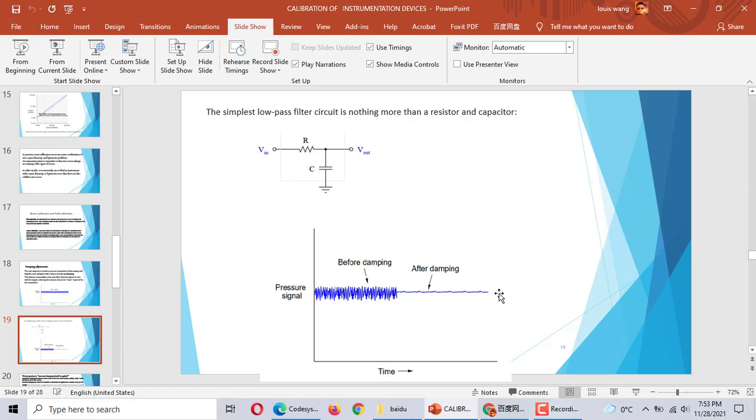Damping sometimes is very important. Okay. For example, before I did a positioner installation, we always cut off the line and shut down the transmitter. We checked everything and found the signal is a 4 to 20 mA signal, but it should have a grounding line connection to the ground.